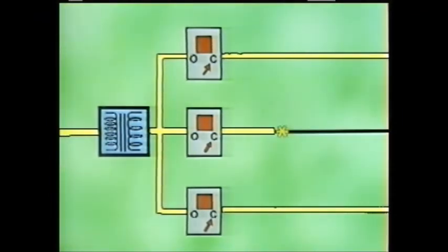However, if the fault does not clear, the current carried by the feeder will continue to flow to ground. This will cause the circuit breaker to open again for a period of time and then close. In some systems, this pattern of opening and closing will continue until the fault is cleared. In most systems, however, the circuit breaker is designed to open and close a set number of times and then lock out. That is, remain open until it is reset manually.